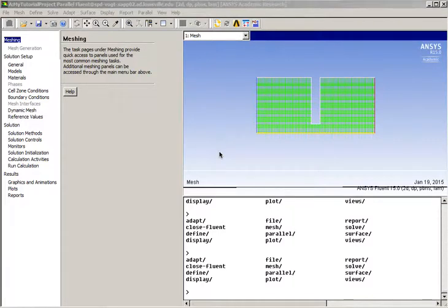In the setup window, you should see your mesh with the different zones labeled in different colors, and you can control how these colors look somewhere in here using display. It just made my pour wall the same color as the other walls, but at least the inlet, outlet, and axis have different colors. It doesn't really matter, but it's nice to see that your named selections came through if they're different colors.